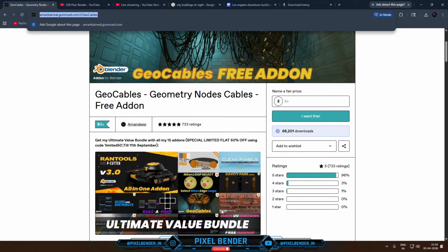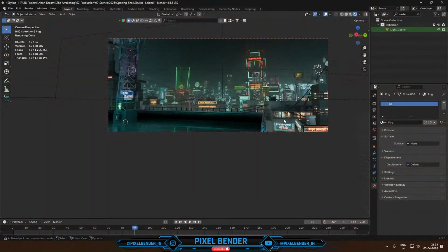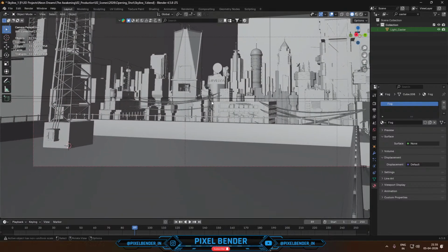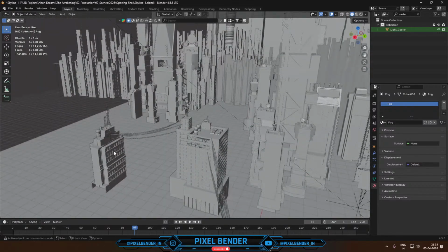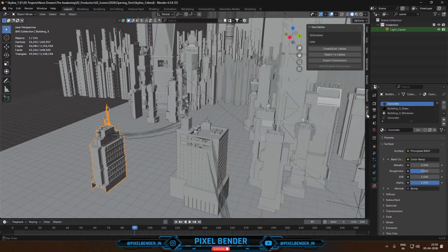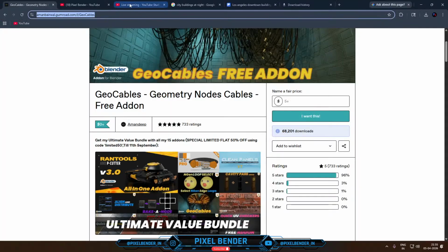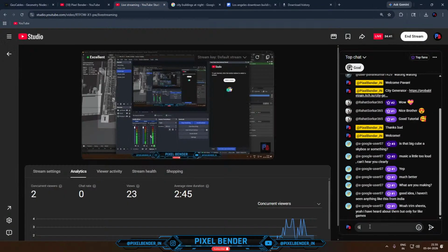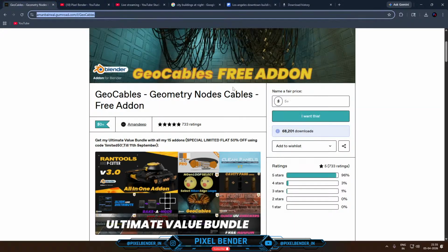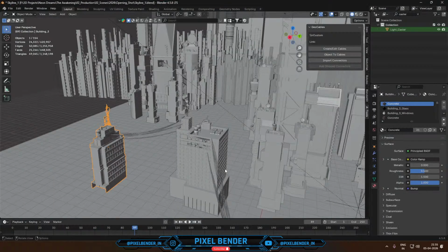Download it, install it in Blender just like any other add-on, and then if you want you can select a surface to start from, or it works without that as well. You will get it under E-tools in your N panel. And you just click on create or edit cables.